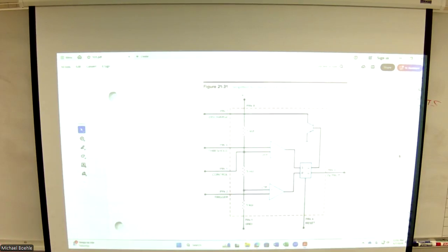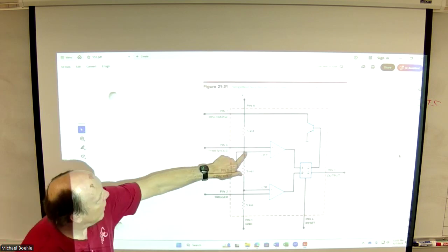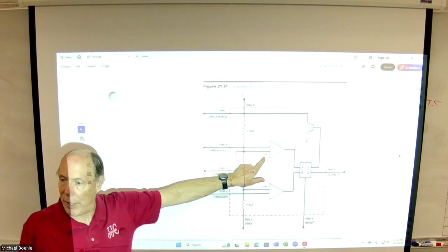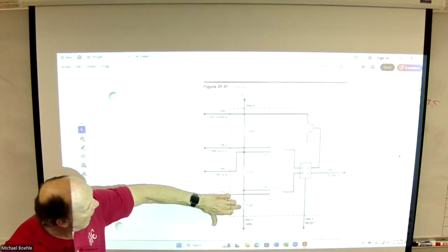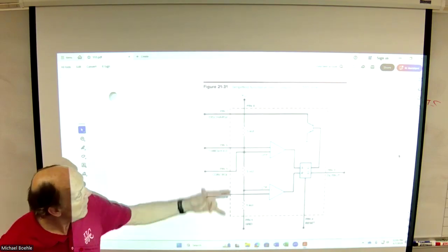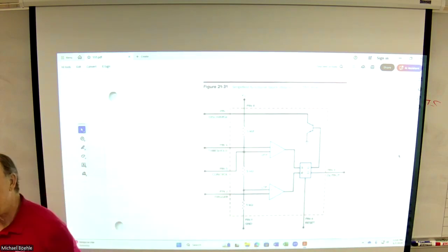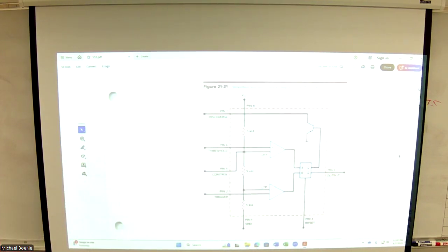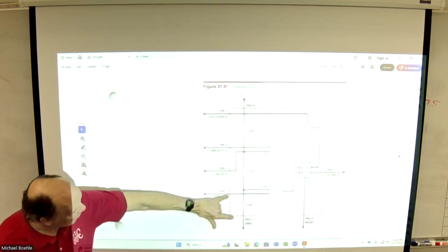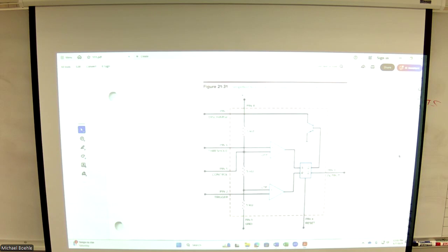So series resistors simply form a voltage divider. So what do we have right here, this point, which is defined as the upper trip point? Well, 5, 5, 5, the total is 15. From ground to this point, 10 divided by 15, 2/3 of whatever VCC is. That's my upper trip point. The lower trip point is across 1/5K, so 5 divided by 15, 1/3. So I have two trip points, 2/3, 1/3 VCC.